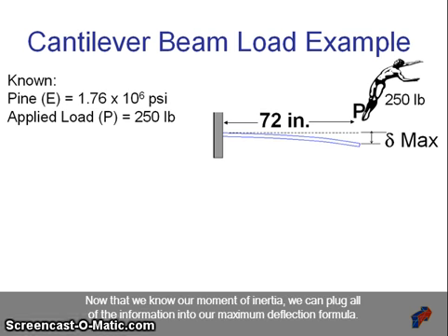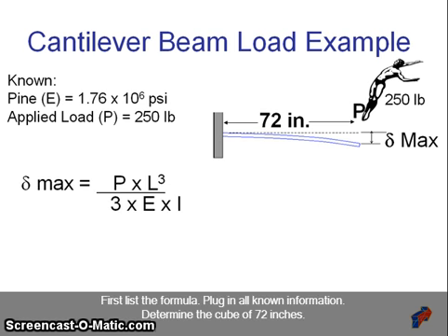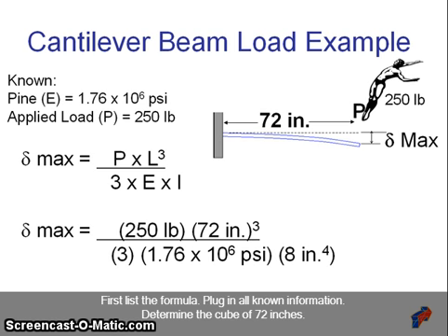Now that we know our moment of inertia, we can plug all the information into our maximum deflection formula. We must find the maximum deflection of a 12-inch by 2-inch pine diving board that is 6 feet long and carries a load of 250 pounds. First, list the formula.